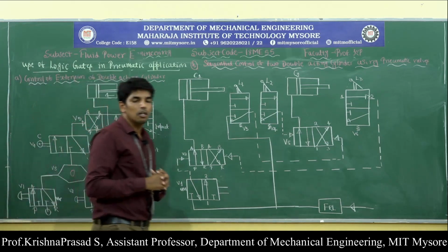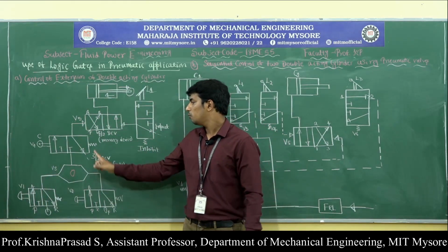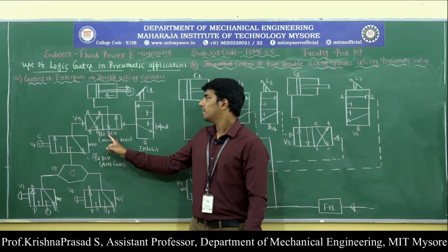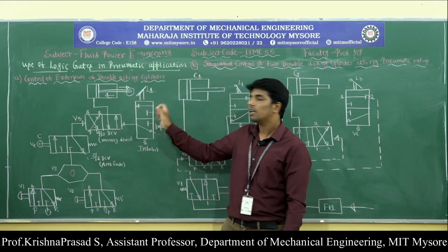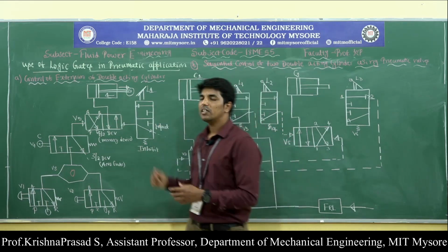So this is the use of logic gates with the help of one OR gate and one AND gate along with the memory device for the extension of the double acting cylinder and retraction of the double acting cylinder. So this is the first condition.